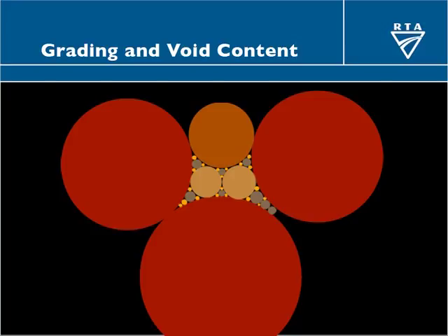And again, if we had yet smaller ones, we can fill part of the remaining voids. Now that can go on for some time. Obviously it could extend to larger particles and then down through the size ranges into much, much smaller particles. And obviously, as we continue with that process, you'll find that the overall strength of the material is increasing because there is more contact and more friction between the various particles, and the void content is decreasing because we're filling them progressively.